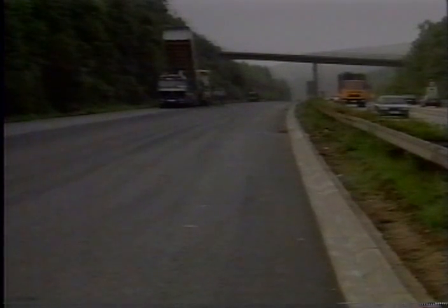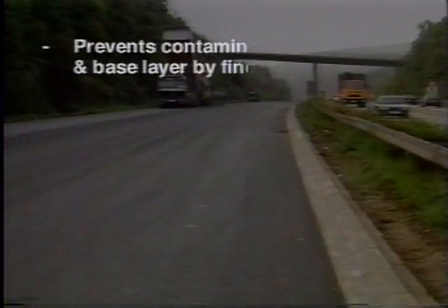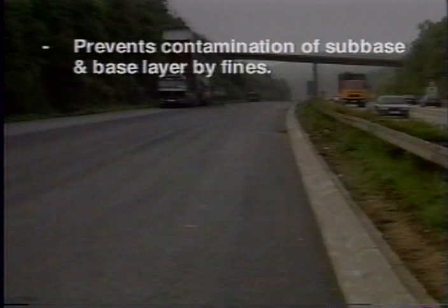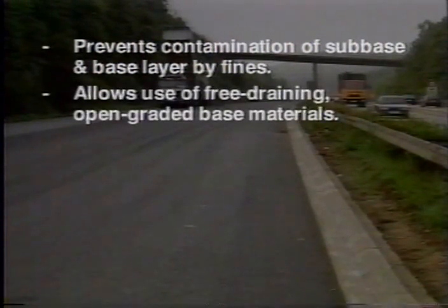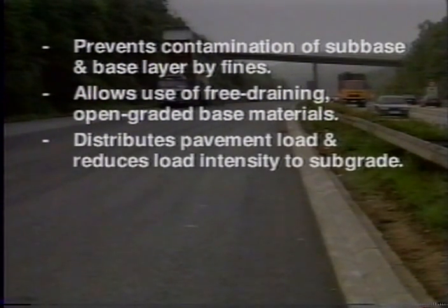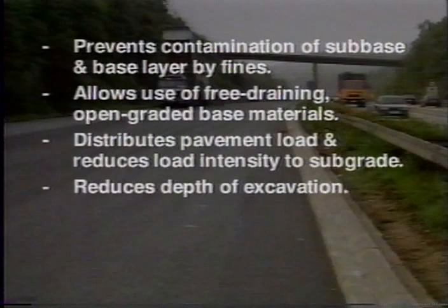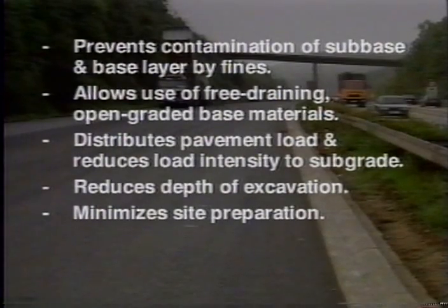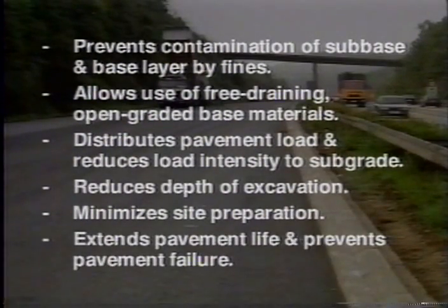A geosynthetic used in paved roads prevents contamination of the subbase and base layer by fines, allows the use of free-draining open-graded base materials, provides stabilization by distributing the pavement load, reducing the load intensity to the subgrade, reduces the depth of excavation required to remove unsuitable subgrade materials, minimizes site preparation, and extends pavement structure life and prevents pavement failure.